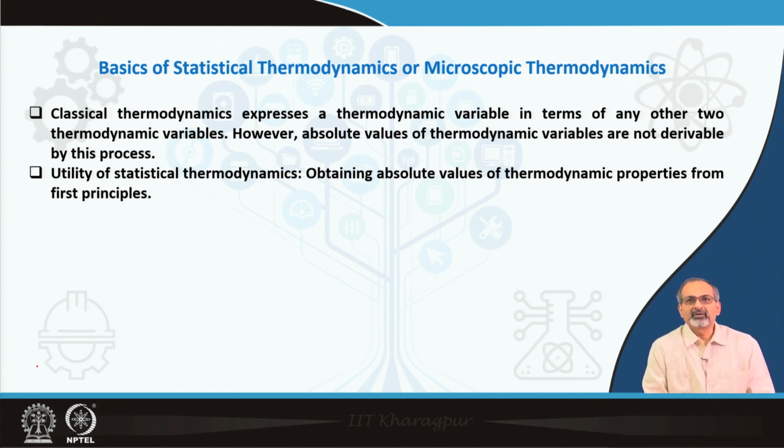While when we look at the microscopic behavior of the thermodynamic system comprising of a large number of gas molecules and atoms, we see that obtaining absolute values of thermodynamic properties is indeed possible and possible from first principles. So, that is one of the prime utilities of statistical thermodynamics. We also get deeper into the molecular picture of the thermodynamic system, and thereby we try to understand the different energy modes, and this becomes very relevant in the context of hypersonic and hypervelocity flows, where the flow gets heated up due to